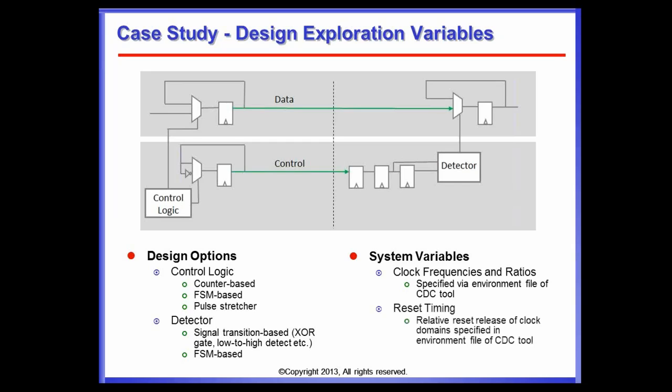Especially when is the reset released, and to which clock is the release synchronized? Is it synchronized among all clock domains, which is usually not the case, or do they have an offset in release, and will this lead to problems? Also, if you cross a clock domain with the reset signal, you can cause metastability, having the reset change at the same time the clock edge shows up on the receiving flop.